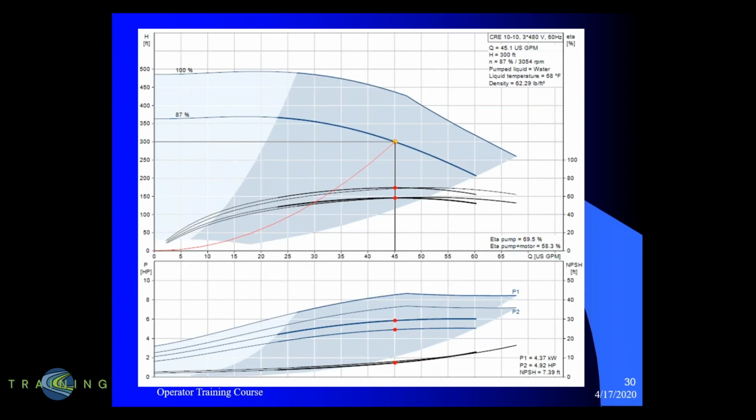On a split case pump, the most that I've ever seen is a 4-stage, and it has 4 impellers added to it. But it's completely dependent on the style of pump, and then you may have to go to a completely different pump application if the number of impellers just doesn't work for you. Hope that answers your question.